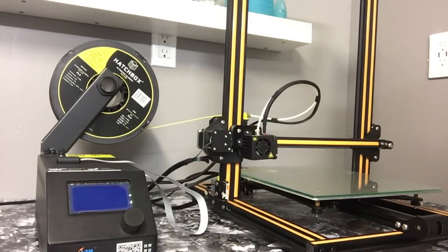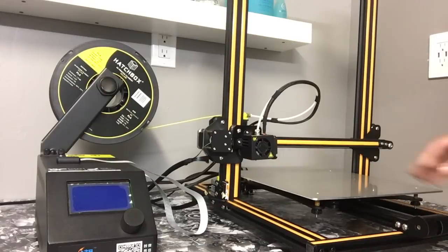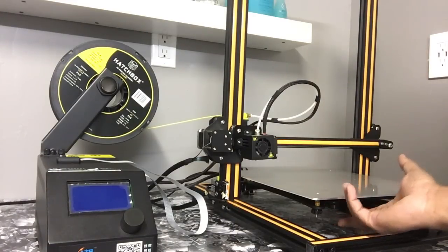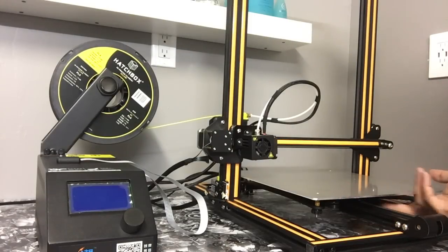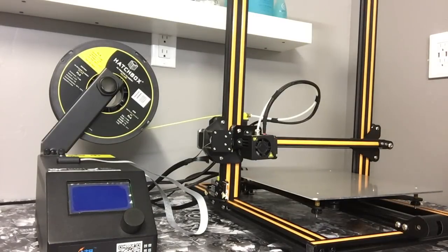Okay, another question I get is, why does my bed wobble? Basically what they're talking about is this part right here. Notice mine does not at this point, but if you watch my very first video, the biggest issue I had at that time is my bed was very wobbly. Down here underneath you will have a couple of wheels. Basically you just have to take a wrench to them and tighten up, and that should fix your bed leveling issues that you might have at the time.